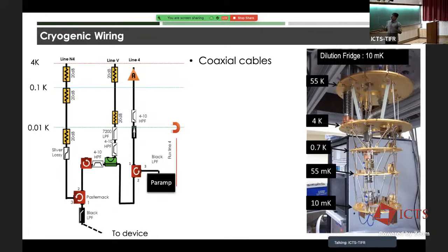In fact, we need to put attenuators specifically. These are these yellow colored things shown here with various values of attenuation. Why is that? Earlier, we were worrying about the heat reaching the low temperature. Now we are worrying about the fact that there is thermal electrical noise at room temperature, which should not make its way down to your device. If you had a straight path with no attenuation, you're never going to do the experiments.